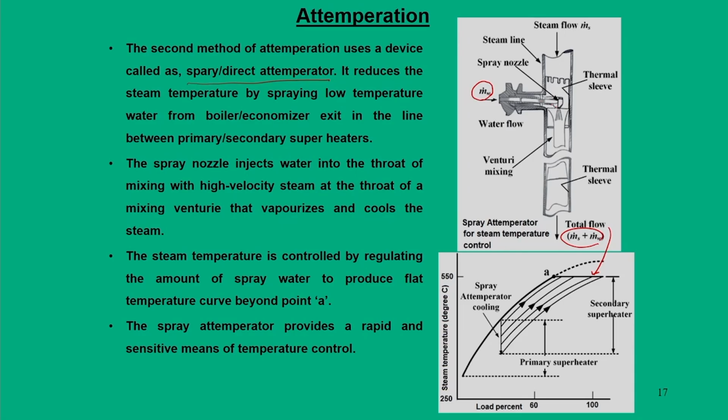This spray nozzle configuration uses Venturi type nozzles, through which water is sprayed, of course, along this steam path. When the steam interacts with the water, its temperature drops.